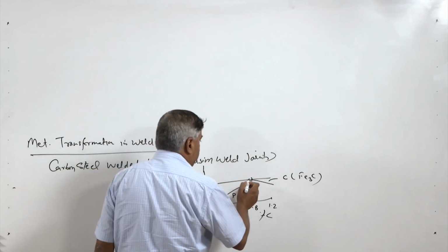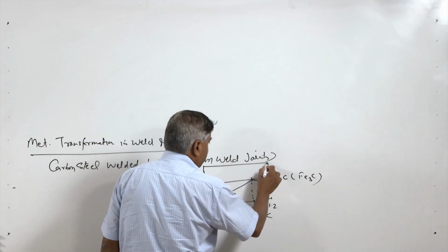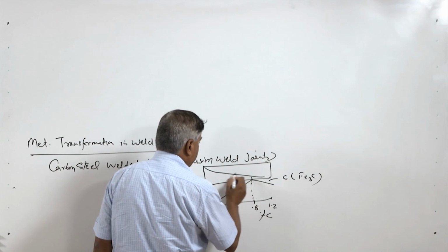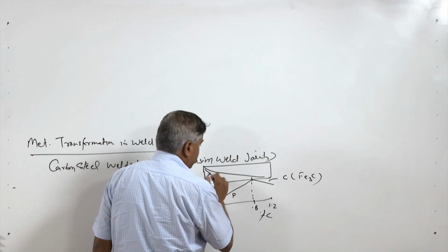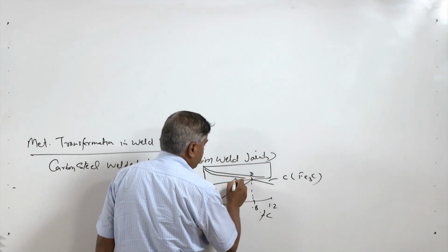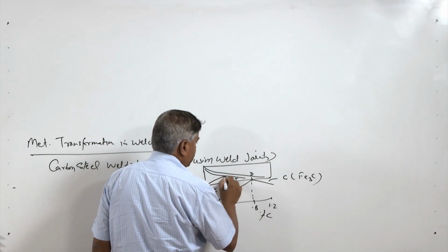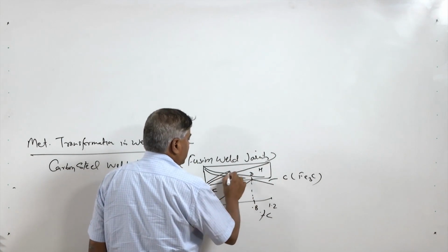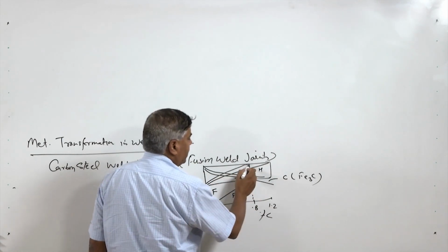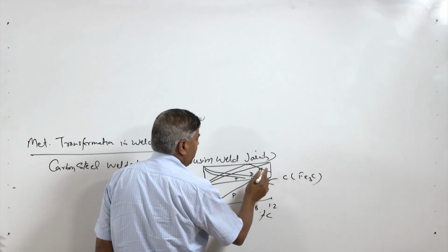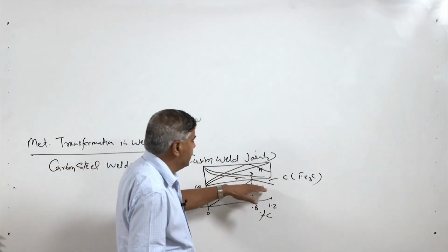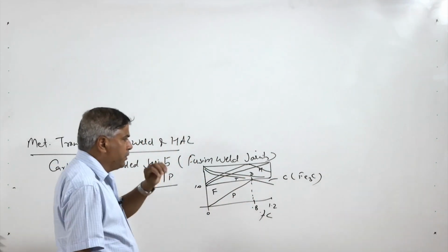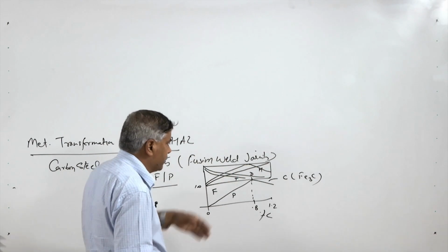This change in properties can also be shown schematically here, that there is a continuous drop in the strength and toughness and the ductility, say ductility and toughness. There is a continuous increase in the hardness, while the tensile strength increases up to the eutectoid point and thereafter starts decreasing, and this decrease is attributed to the formation of the cementite along the boundary of the pearlite, that is the pro-eutectoid phase which is formed along the grain boundaries.